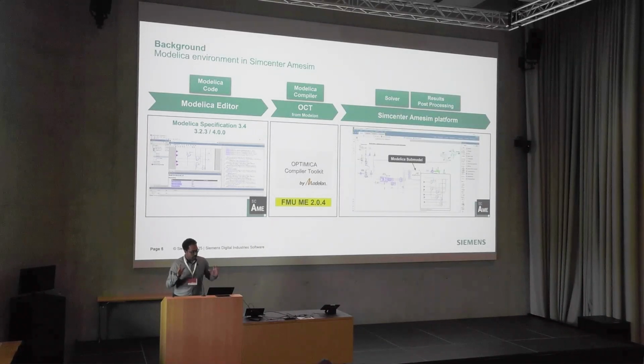Thanks to this compiler, we can import the Modelica code or Modelica system into Amesim, thanks to the FMI generated by the compiler. At this moment, when we are in Amesim, we are causal because we generated the FMU, and then we can link the different signals between this FMU and the Amesim submodels, and then we can simulate. This is the basic integration of the Modelica language in the platform.